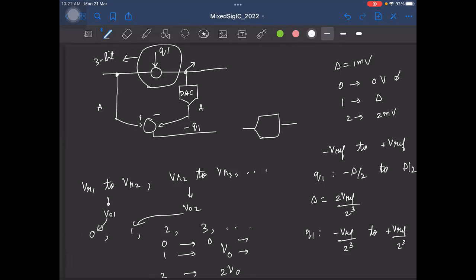Is that fine? So now again, if you use an ADC here, this ADC will be operating at the same reference voltage level, right? So if you want to get complete resolution of this ADC, you want the input to also span the entire range. Because the quantization noise is only within this small range.